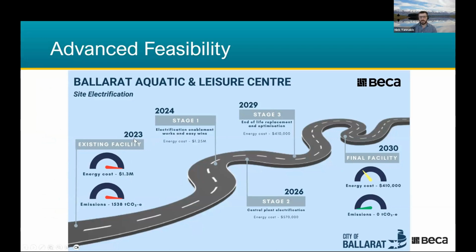They had to upgrade the HVAC system, and what they ended up doing in stages like that, upgrading the HVAC system first, actually ended up saving a couple of $100,000 in operational costs. But the bigger thing is why you did that first in the stage: it saved about 400 kilowatts of plant size by fixing that one element. So you actually want to do that first to reduce the capital cost expenditure in the second stage, of the size of the heat pumps required to go into the facility. Otherwise, you overcapitalize on that.